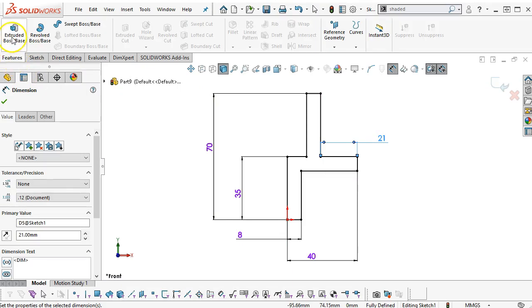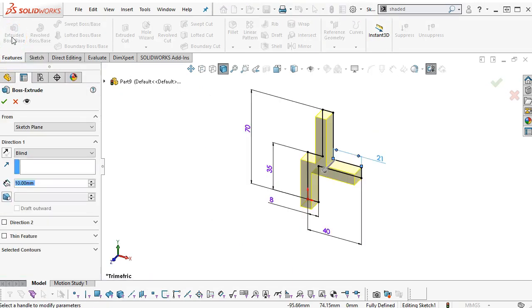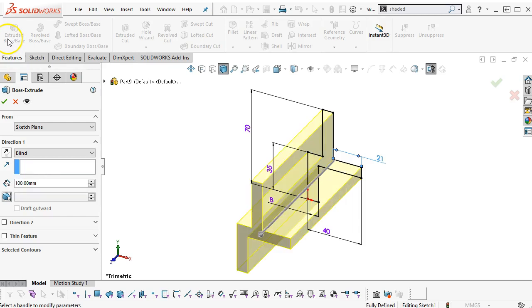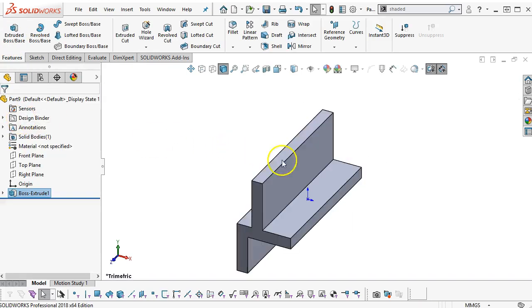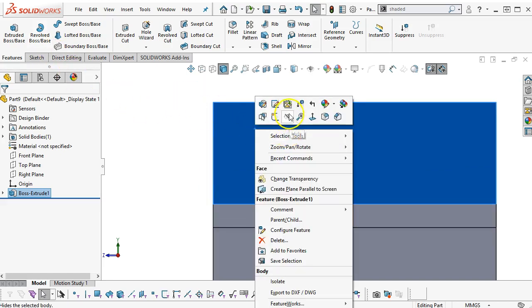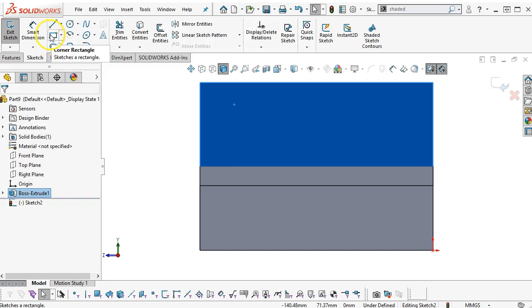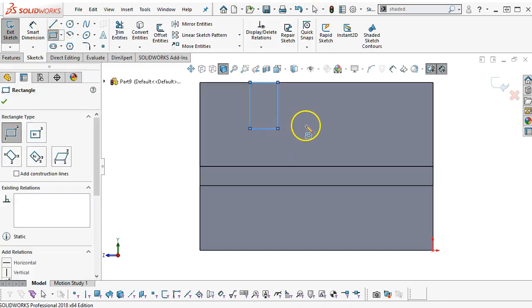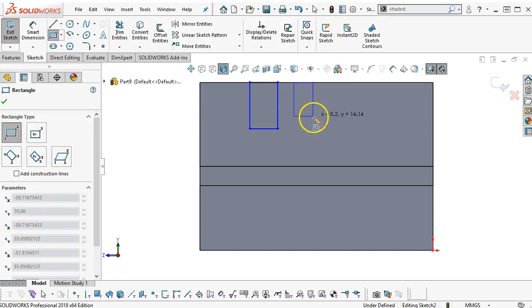Okay, that gets extruded. Let's see, there's 1, 2, 3, 4. It may not be a great advantage to having a pattern here, so at least if I can mirror, well, it still doesn't really matter if I go mid-plane or off of one side. So 100 millimeters. Open up a sketch on the face. I'm going to generate the rectangles.